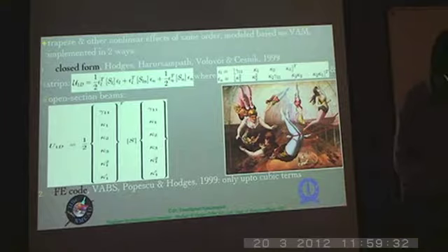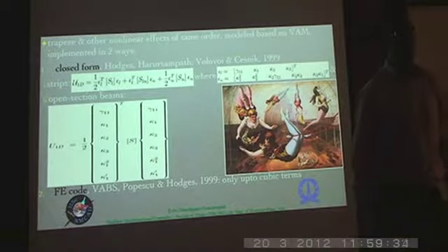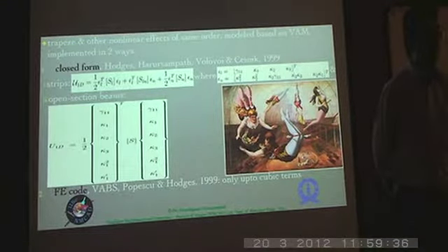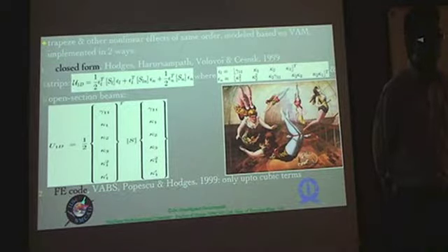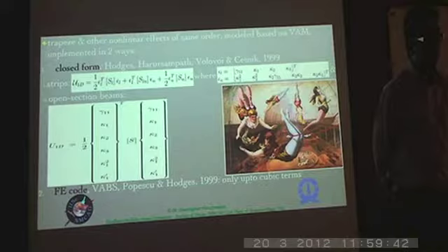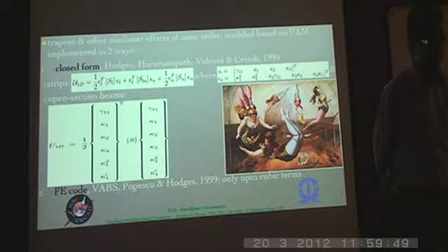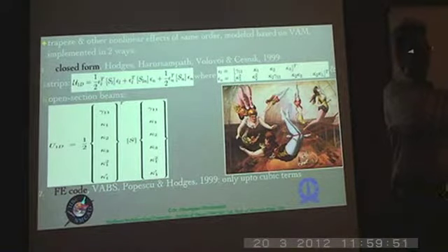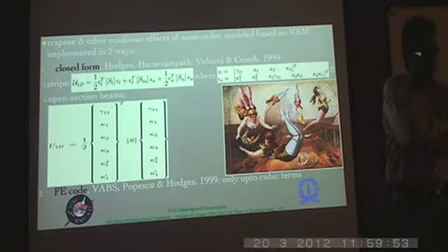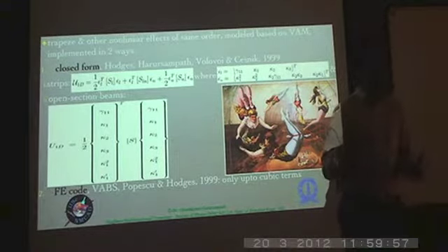Yes, please. So for strips, whatever I said, that we can get more nonlinearities as compared to the thick sections. In thick sections, obviously, the kappa 1, kappa 2 curvatures may be less because of thickness, bending curvatures, kappa 2 or kappa 3. But there may be shear couplings because of shears. Deformation may be large. The couplings will be there, but they are not non-linear.